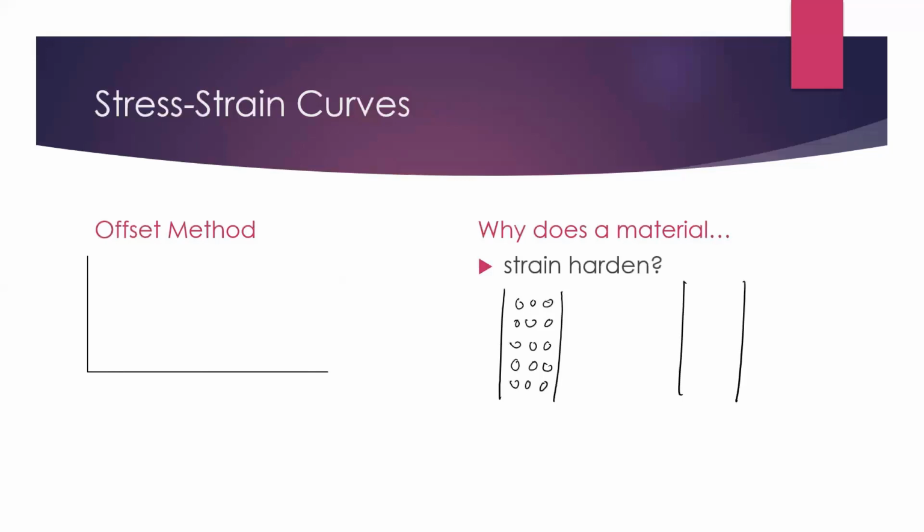But at a certain point, they're no longer going to be aligned in this nice lattice. So you might have elements that are moving past each other. So they move out of their original molecular form and they actually slide past each other. And that's what is happening at the molecular level when you have strain or when you have yielding. And that's why they're not going to go back to their original position all the way, and so that's why you have that permanent deformation.